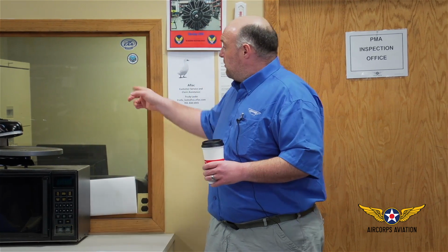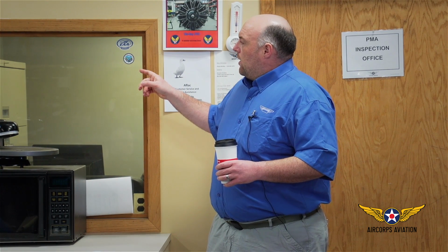You make sure that your part is listed on the 6-column supplement. All those 6-column supplements will be available on the server, and they'll also be in the top drawer in here, in what we call the FAA airworthiness data file. In that file is going to be all the letters that went back and forth to the FAA, the engineering reports, any 8110-3 forms that were signed to approve the engineering data, results of any conformity inspections that were accomplished, and a copy of the FAA 6-column letter authorizing you for production. It's your airworthiness file for that part.